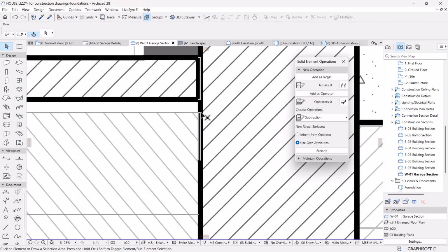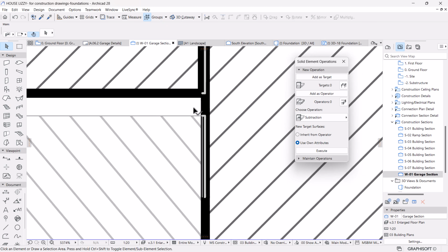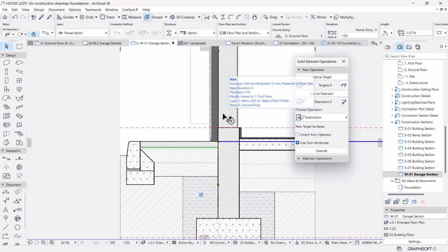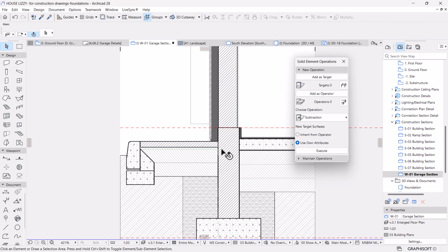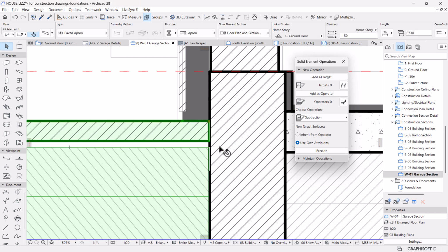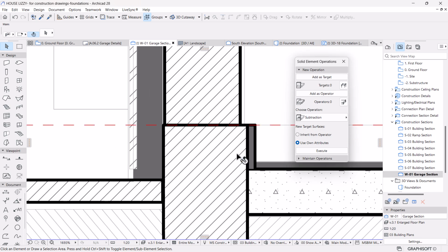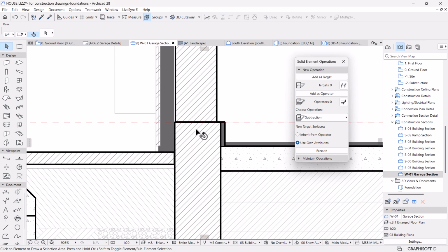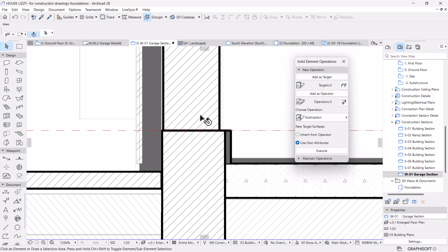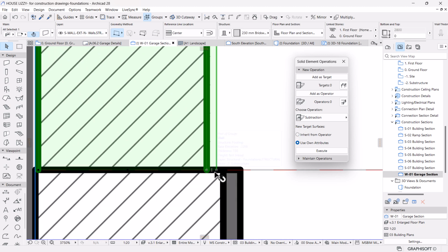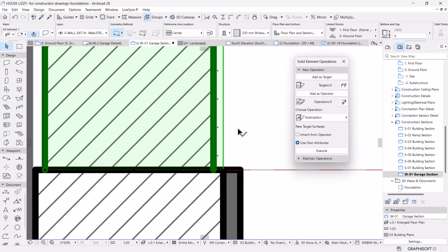But there's a bit of a clash here. What is this material for? This is what? Okay, I need to bring it to front, maybe. Yes, I just needed to bring it to front. And oh, I see. You know why? When we removed the skin of plaster on the other side, that changed the thickness of our wall. So if you see here, we have that captured. But this needs to be right there, straight to that.